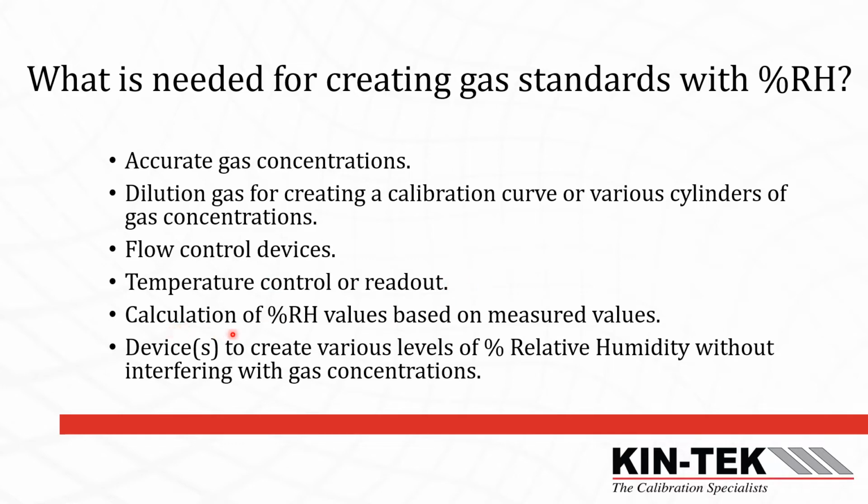You also are going to have to calculate the percent RH values based on measured values. So whether you're measuring the temperature of the room or the temperature where you're testing, and/or pressure, or anything that's going on in the atmosphere of what you're calibrating, you're going to have to measure those and then calculate them on the fly. You would also need devices to create various percent relative humidity. So that's the key there.